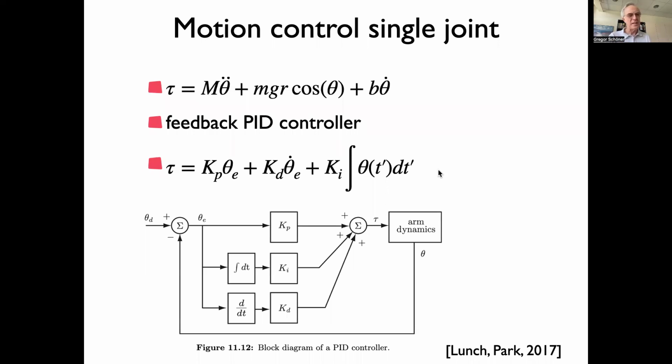For instance, if there is an unexpected obstacle, let's say your arm is hindered because the surface is not where you thought it was, and so you're not reaching the position because it is a little inside that surface, that term would keep ramping up the torque to reduce the error to zero. So if the surface is something fragile, for instance, the robot arm would keep increasing the force with which it presses against that surface and do something really bad, like break something. Clearly, you'd have to put some limit on that. So the integral term, you can see, is a little bit problematic.